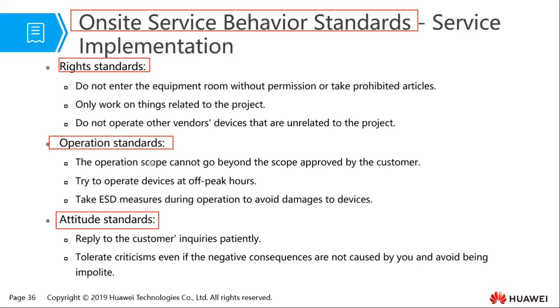Operation standards. So the operation scope cannot go beyond the scope approved by the customer. Then try to operate devices at off-peak hours. We already said this. Then take electrostatic discharge measures during operation to avoid damages to devices. So the on-site engineer is always supposed to wear an electrostatic discharge wrist strap so that they don't damage the devices due to electrostatic discharge.